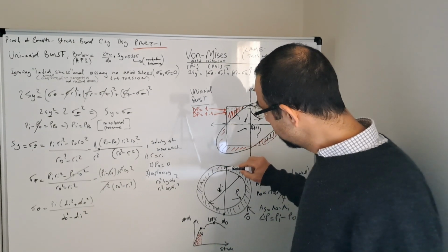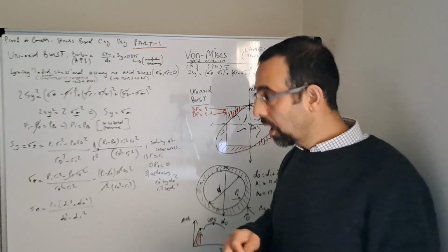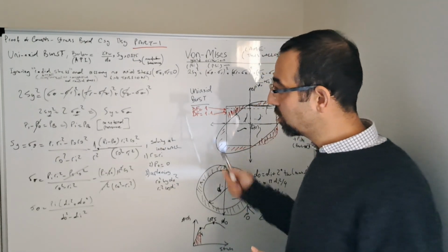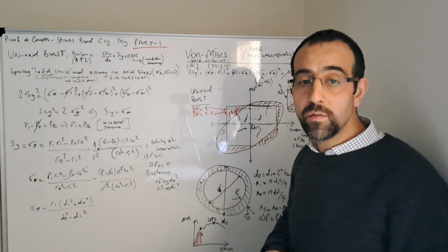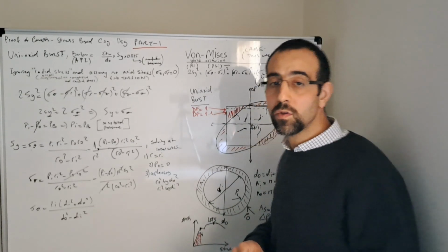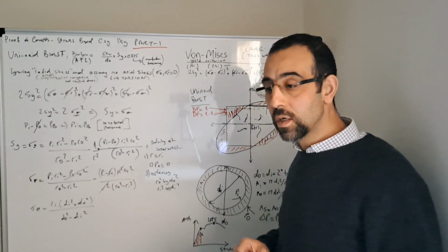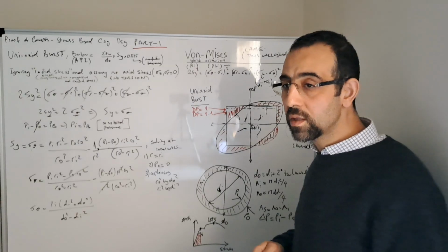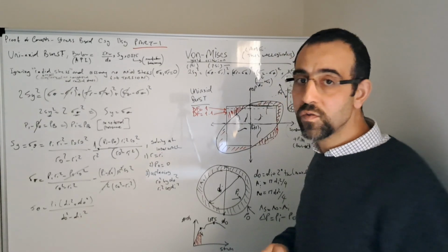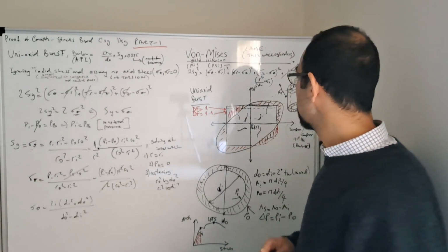The wall thickness that we refer to here is the nominal wall thickness, and we are going to touch base on that when we derive the Barlow equation, because usually API accounts for a 12.5% manufacturing tolerance on the wall thickness. So you will need to use a correction factor accordingly.